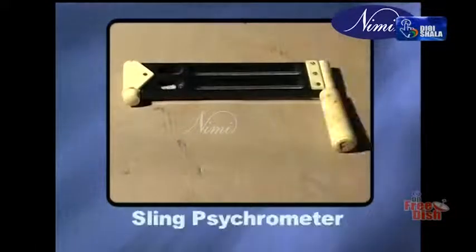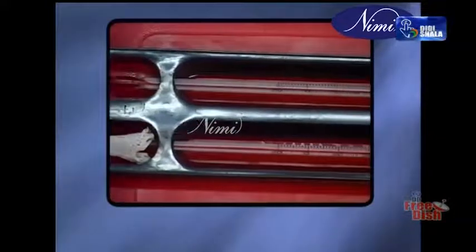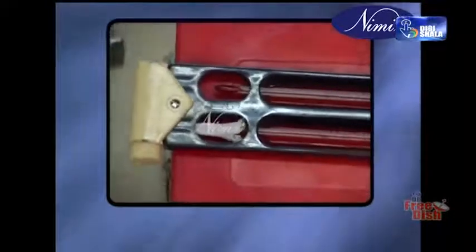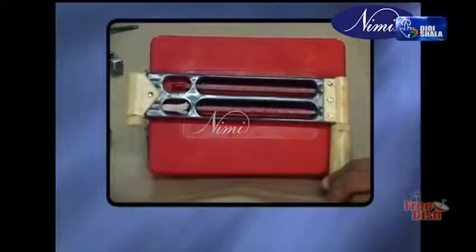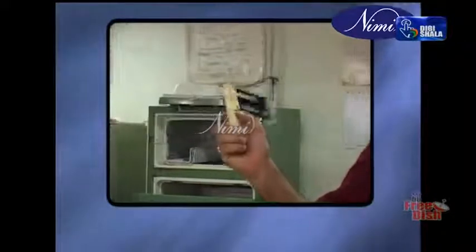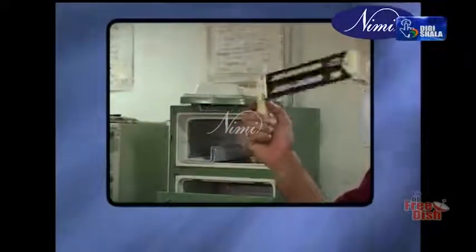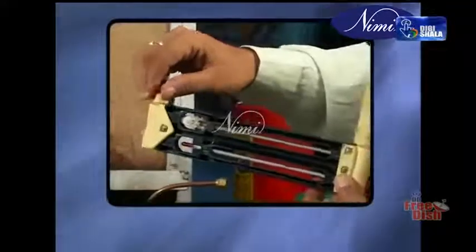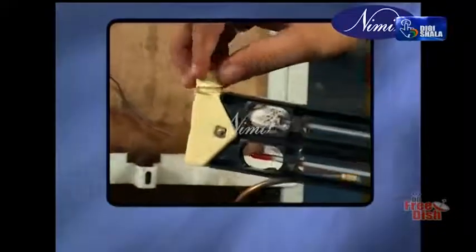Sling psychrometer. Relative humidity is measured by an instrument known as the sling psychrometer. This instrument consists of two ordinary thermometers securely fastened in a frame which is attached by chain. By means of this chain, the instrument can be rapidly whirled around so that it comes in contact with maximum amount of air. Around the bulb of one thermometer is a wick cloth which is moistened with water when taking a reading.